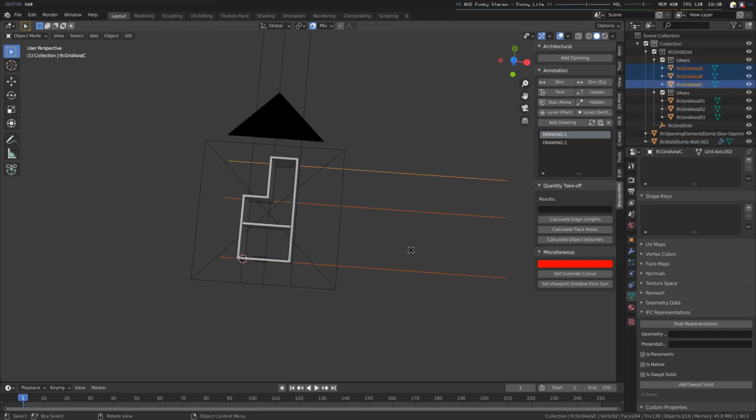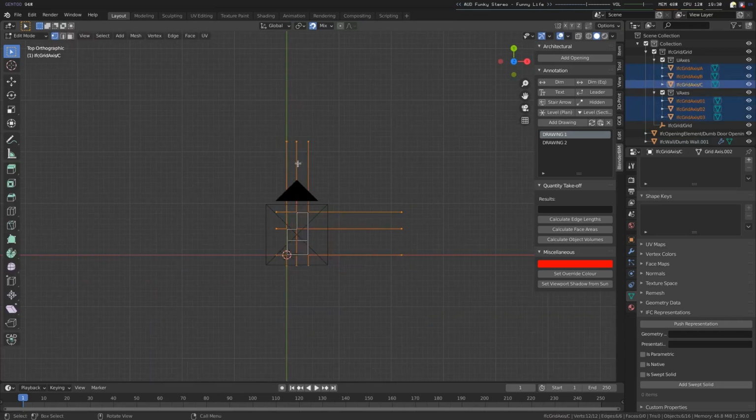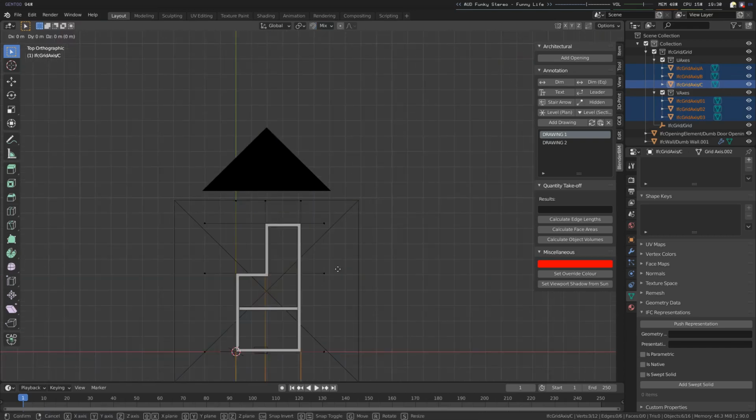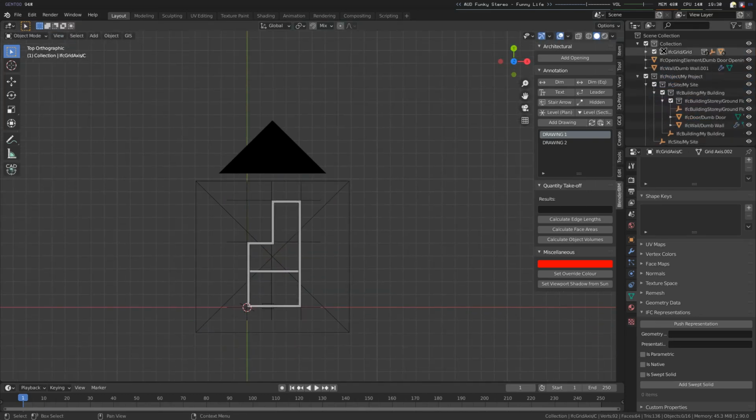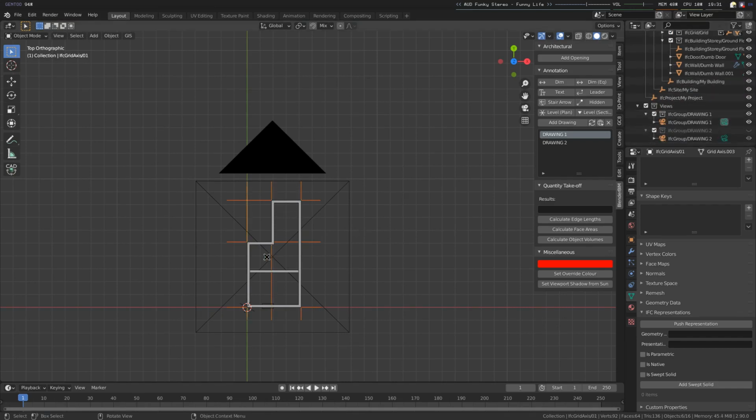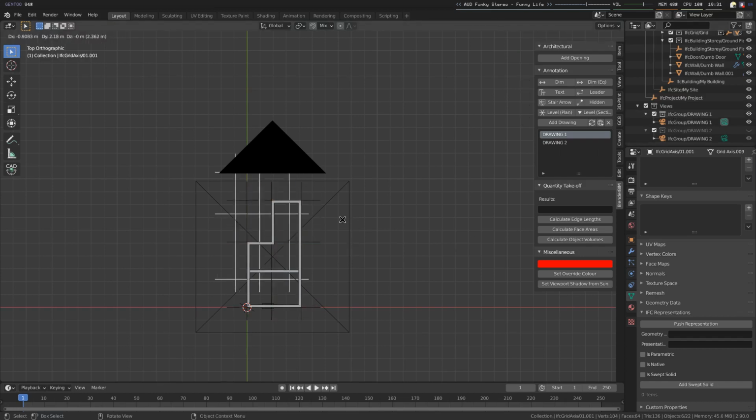And I might also pull these grids in because they are extending far past the drawing boundaries. And now I'm going to place this grid in the building object because it applies to that building, and finish categorizing the new wall that I have added, and go and re-export my IFC file. Now, in order for grids to show up, I also need these grids to be explicitly placed inside the view. So I will place that in this IFC view drawing 1 object.